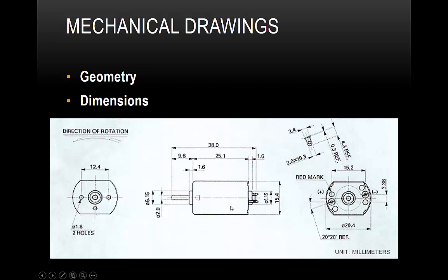So the first kind of dimension we're going to look at is what's called linear dimensions. And linear dimensions just represent length. They always start with some kind of anchor. So these anchors are the lines that go in between, and the leader, which shows us where the extents of the dimension are, and there's always a number on it. Right? And the number isn't always centered. Sometimes it's offset. Sometimes we have one like this where the number is too big, so it's going to pop outside. So this 1.6 represents the distance between these two arrows that are outside the anchors, and that's how we represent those.